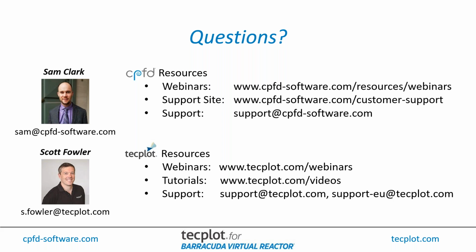But at least in Tecplot, it might make sense for them to have the same start and end time for your case. But when you do the solution time linking between the two frames, they can be fairly independent, and Tecplot actually works pretty well with that scenario. We've made some specific decisions in Tecplot about how it deals with transient or unsteady data to work with fluid structure interaction, and oftentimes those have different time step intervals as well. So I think you should be fine there.